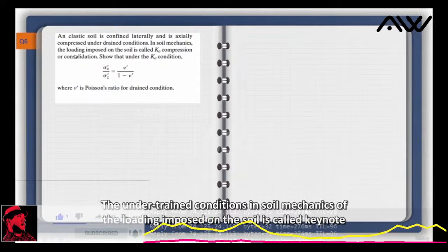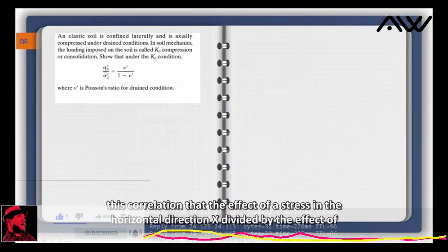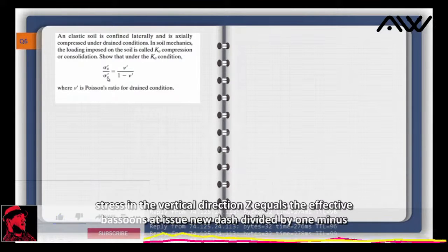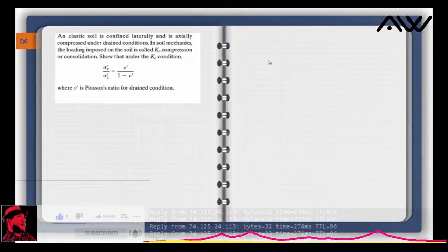In soil mechanics, the loading imposed on the soil is called K-naught compression for this particular case, or consolidation. Show that under the K-naught condition we have this correlation, that the effective stress in the horizontal direction X divided by the effective stress in the vertical direction Z equals the effective Poisson's ratio mu dash divided by 1 minus mu dash. This is Poisson's ratio for drained conditions, or we call it the effective Poisson's ratio.